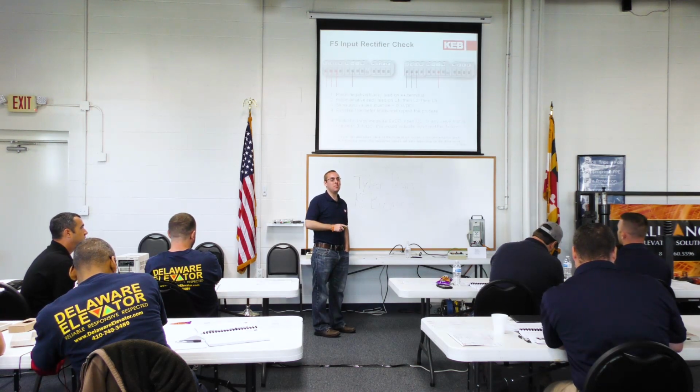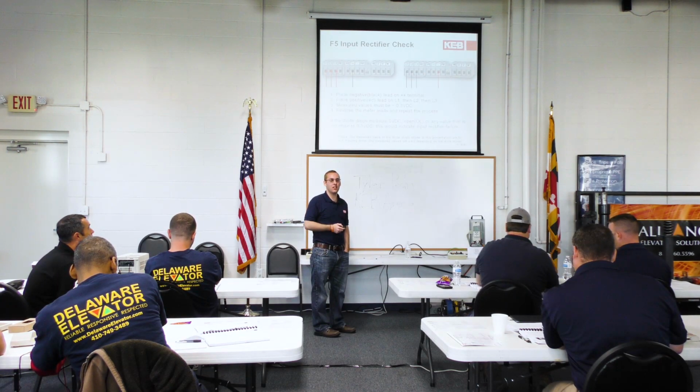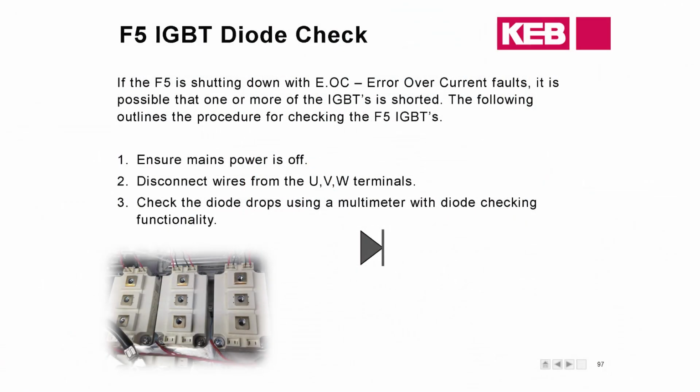Okay, so that's the input side of things. That's something you can do to make sure the rectifiers are okay. All right, the next one: if you're getting the EOC, the overcurrent, you've disconnected the motor leads from the U, V, and W terminals on the drive, and you're still getting the overcurrent, so it's likely something on the drive is causing that. We can do the same style of check. It's going to be the same diode check.